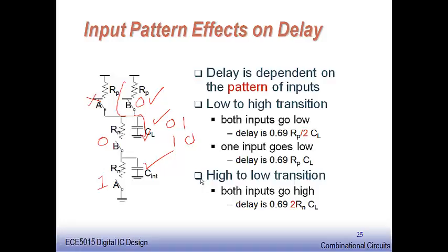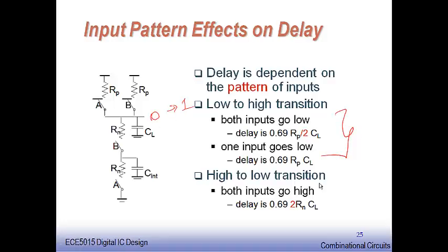The next case would be, I have put here the conditions, the discussion. It went only for low to high transition, that is, taking your output to be presently low and it goes towards the high logic state as discussed here. And let us take the condition of the high to low transition, the TP-HL. This was the TP-LH case. Now what will happen in the TP-HL case? Let us take combinations. I have both to be ones, both were off, and whatever I have here will be discharged, whatever I have here will be discharged.